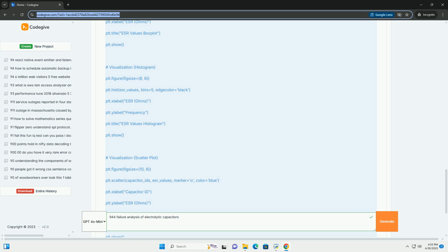Capacitance measurement. Use a capacitance meter to measure the capacitance of each capacitor. Compare the measured values to the rated values. 6. Replacement. If any of the capacitors have significantly elevated ESR or reduced capacitance, replace them with new capacitors of the same or higher voltage rating and equivalent or lower ESR. Use high-quality, low ESR capacitors designed for switching power supplies or automotive applications. 7. Reassembly and testing. Reassemble the relay and test its functionality in the car.